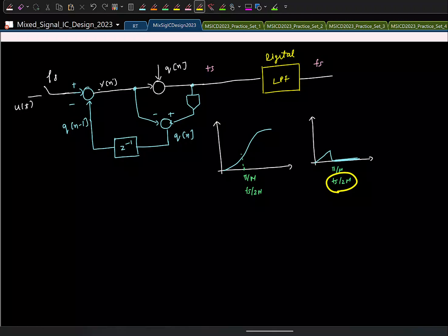So what is usually done is after this you reduce the sampling rate, and that is done by what is called downsampling. That simply discards samples. Let us say this is giving you x of 0, x of 1, x of 2. It only picks the 0th sample, mth sample, 2mth sample and so on. It discards all the other samples. This way you reduce the sampling rate.